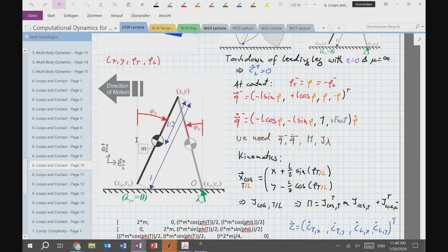I can also assume that the foot leaves the ground, then there's no collision, right? Then I would only compute the collision at the front. I will not have a collision impulse in the back. But again, I made an assumption, and that assumption is only valid if afterwards the contact point leaves the ground. So we get multiple possible outcomes.